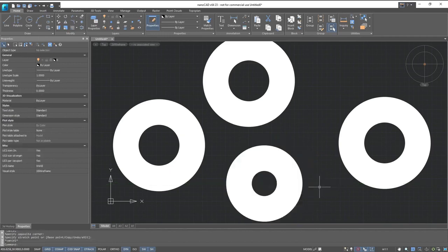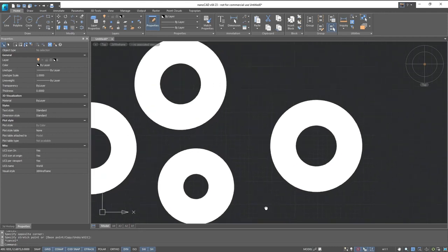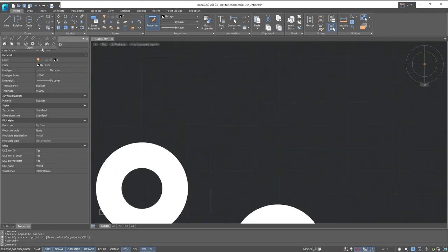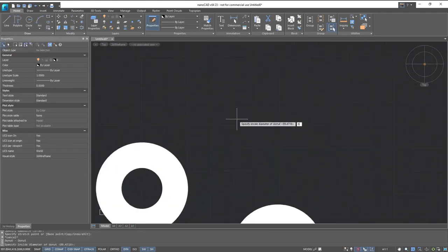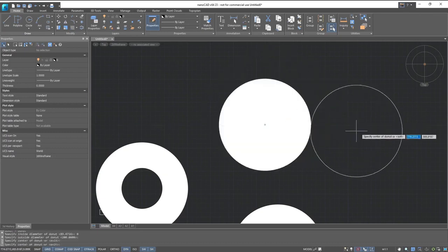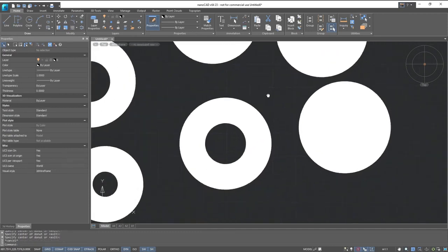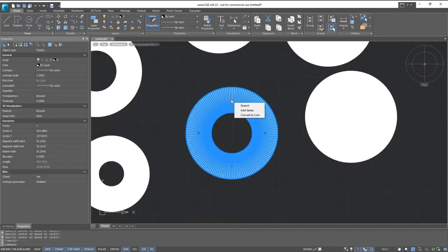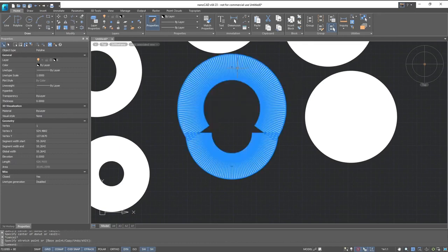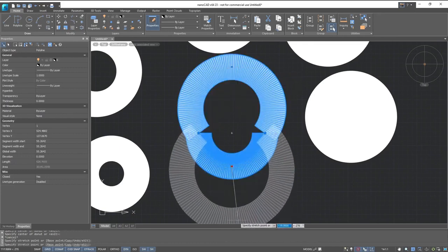To get a fully painted contour, you must set the value of the inside diameter as 0. Let's try it. Inside diameter 0. Enter. Outside diameter. In this case you get a fully painted ring. We can also see that these are indeed two polylines that are connected at their ends. And we can change the appearance of the ring according to what we need.